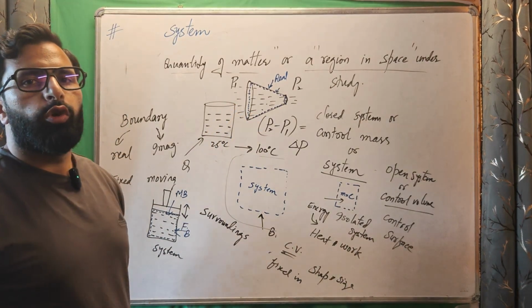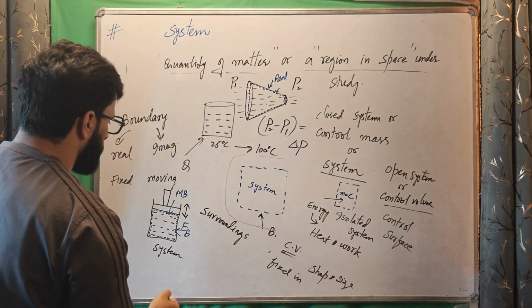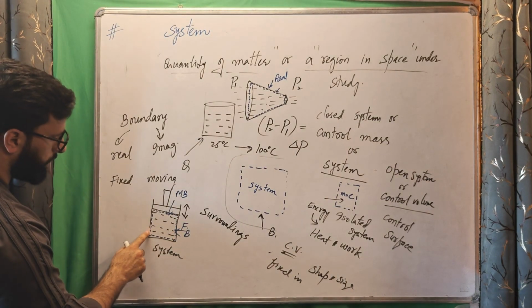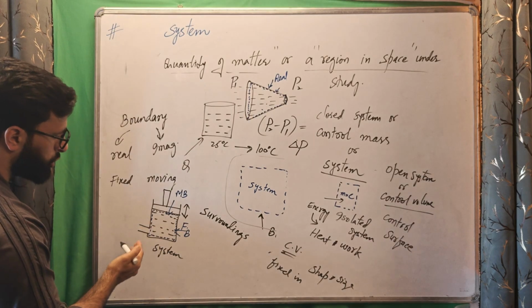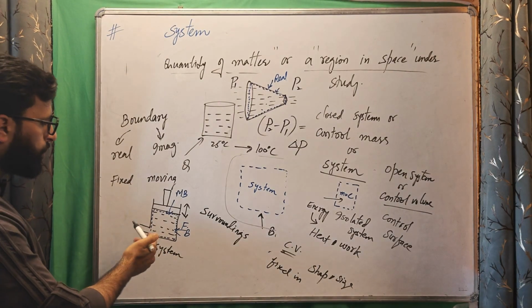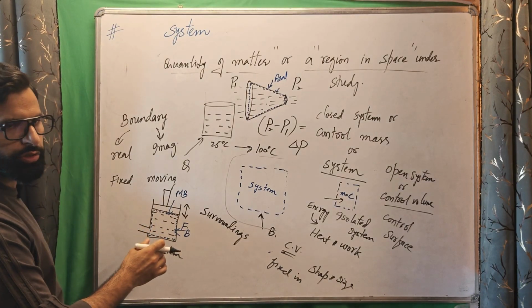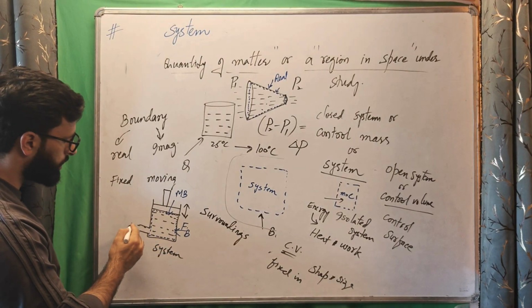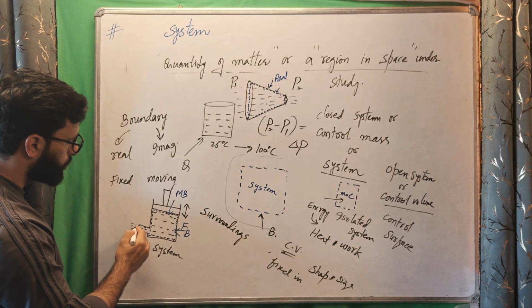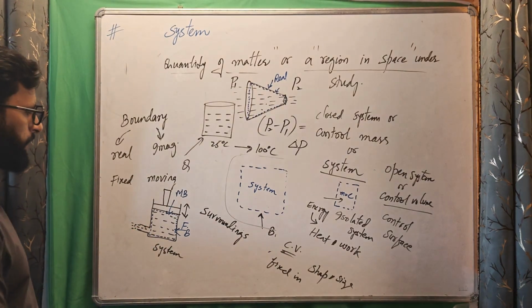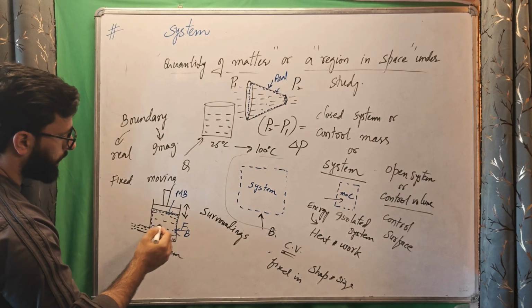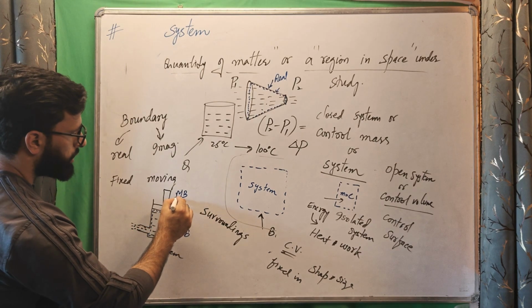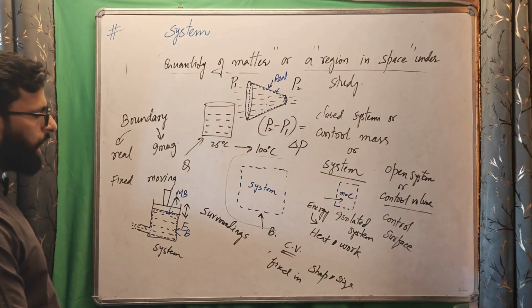But the control volumes can be moving as well. For example, if this was a system, but if we let gas flow in, so this becomes a control volume instead of a system, because now we are letting gas in. So quantity of matter is no longer fixed. Now this is the control volume, this blue line. When the gas flows in, it pushes the piston outwards.